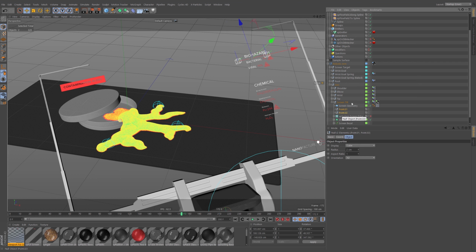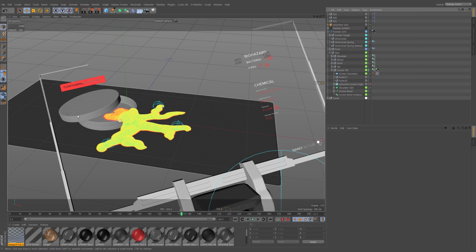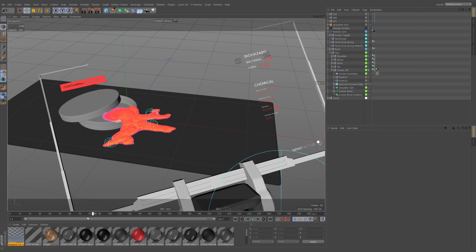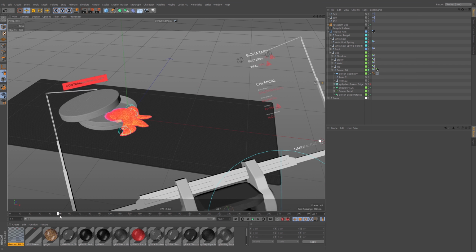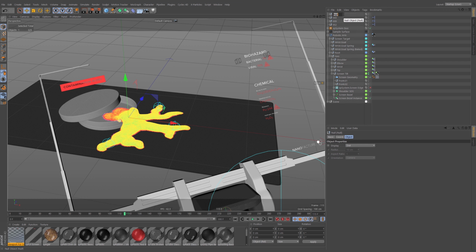Okay. And now what we're going to do is connect these up using tracer objects. So up here, we're going to create a new null, because we can create this all outside of this hierarchy. If I move the arm, you'll see those now move with the arm. Excellent. I'm going to add another null there, and we'll call this our, what's this going to be called? Our labels, I guess? Or particle labels, something like that. And we're going to drop those in there.